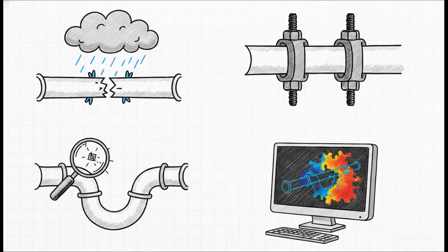The source material leaves us with a really clear checklist for best practices here. First off, actively identify vulnerable pipes. We're talking about anything outside exposed to the weather, or pipes carrying mixed phases of gas and liquid. Second, use rigid hold-down supports to physically restrain that bowing effect. Third, design the system with enough flexibility to handle the curvature if it does actually happen. You also want to pay special attention to sudden thermal drops near delicate welds or flanges. And finally, as a general rule of thumb, always run a test simulation assuming a 50 degrees Celsius temperature differential for any exposed pipe operating over 200 degrees.